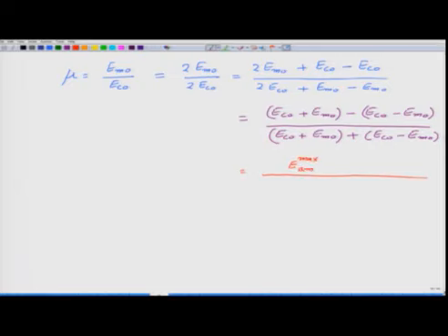amplitude modulated electric field. If you remember, the electric field of the amplitude modulated wave was given by E c naught plus E m naught sine of omega m t, this was the amplitude, and this thing was multiplied by sine of omega c t, where omega c is the carrier frequency, which does not change. So, the wave was given by this.